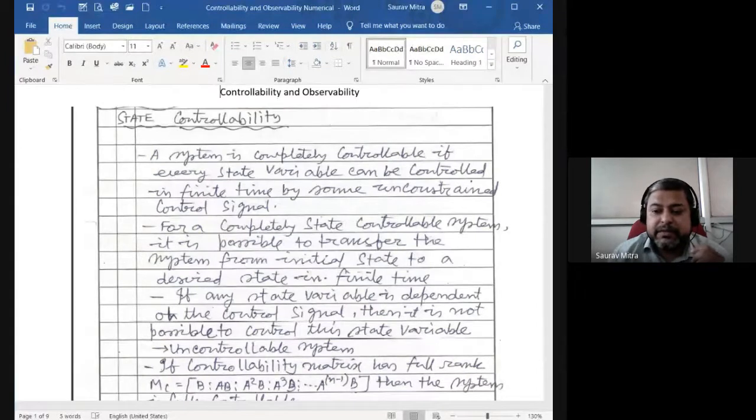After you find the transfer function, then you find the companion form of it. This is not difficult, but we have done 3-4 numericals for second order and third order systems. From the transfer function, how can you find the state variable model? There was an intermediate step, which was called the companion form. I had shown you 2-3 numericals that we have solved. There was x(t), there was y(t), and always we were taking y(t) equal to q1(t).